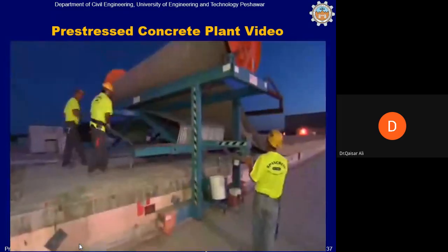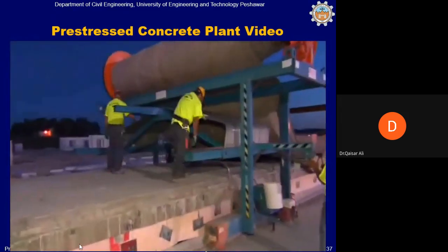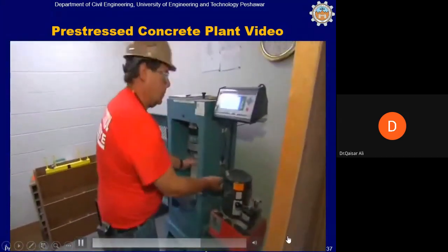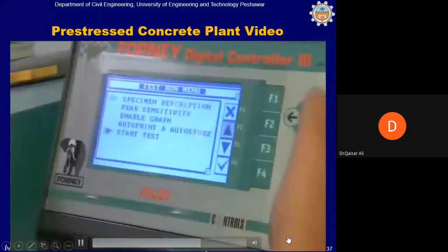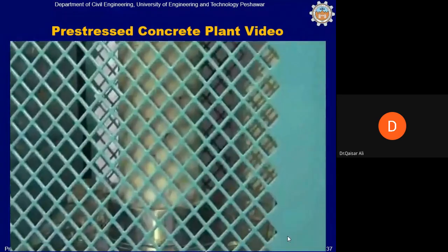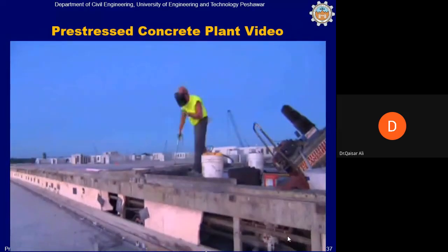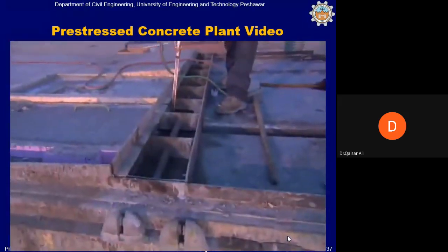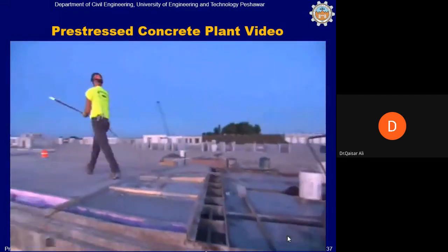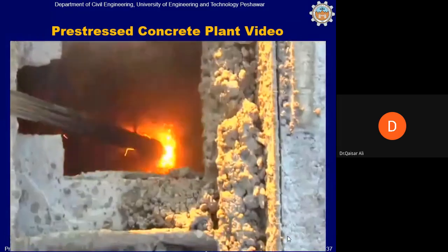After 12 to 16 hours of curing, the Ts are ready to be stripped. The QC department first tests the concrete to be sure it has achieved the strength required to detension the strands, typically 3,500 psi. This is a typical test being conducted. The strands are detensioned in a specific sequence established by the QC department or the plant engineer. Here, personnel are positioned at each end of the bed and at some of the intermediate bulkhead locations. On a signal, they burn the strand at each end.